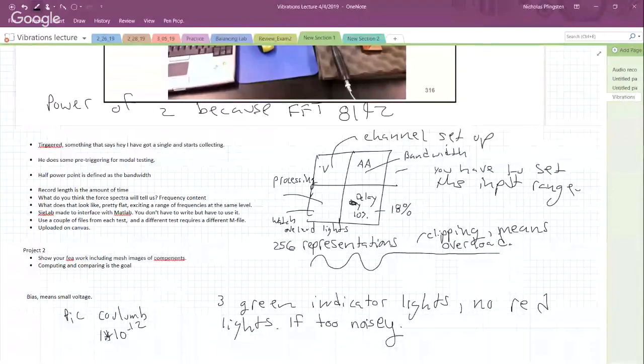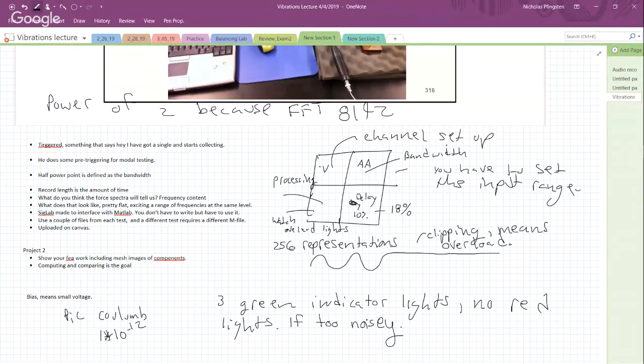We can also look at the spectra. So I'm going to go back to channel 1. There's my impulse. And now I want to look at the magnitude of the spectra. What I see there, it's pretty flat out to like 800, almost 1,000 hertz. If I put a steel tip on instead of a plastic tip, it would expand that out. And I might do that. Plastic.